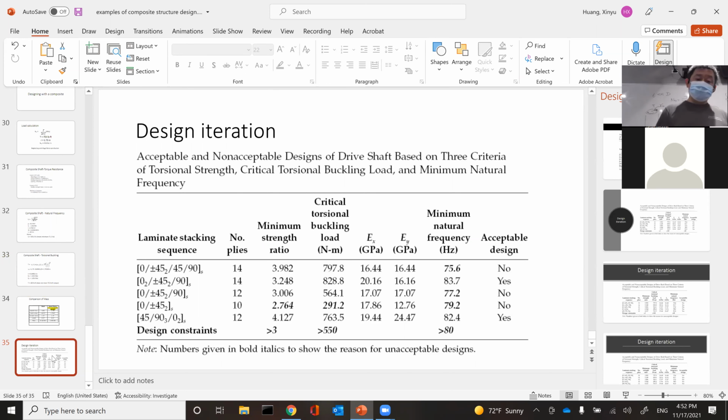All the layouts started here are symmetric. So there is no fixed correct solution. There are many possible solutions. All you need to do is propose your layout, do your calculations, and evaluate the results in terms of 3 criteria. Is it strong enough? Would it buckle? Would it vibrate? And you pick the ones obviously with probably lower cost, in terms of small amount of material.